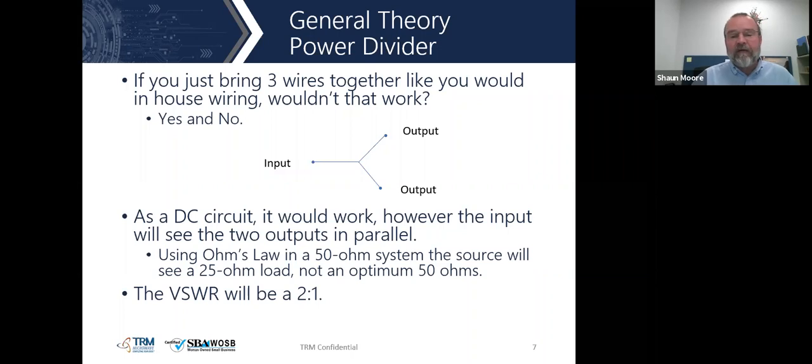At a DC level, and really from a power divider standpoint for microwave circuits, we want to make sure that all sources and receivers have the same impedance. That ensures maximum power transfer from the source to the receiver. The universal impedance that microwaves work with is 50 ohms.